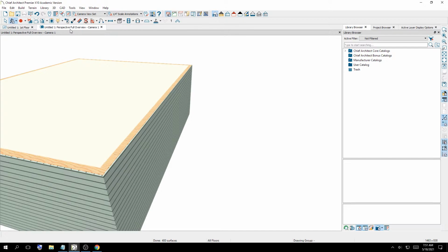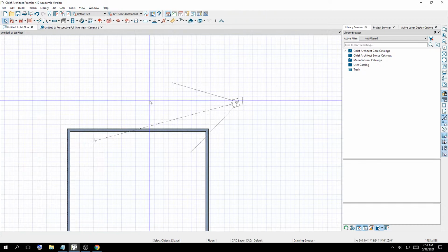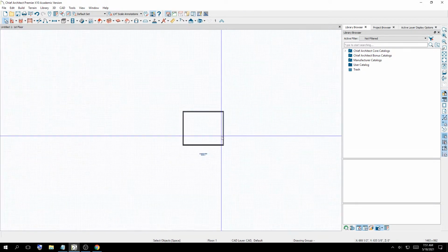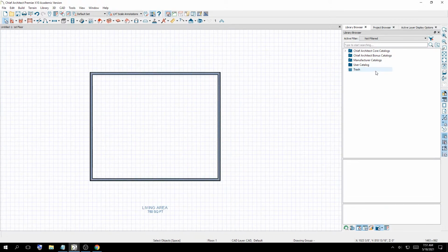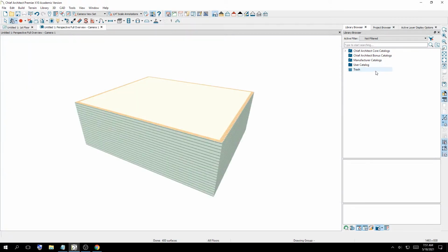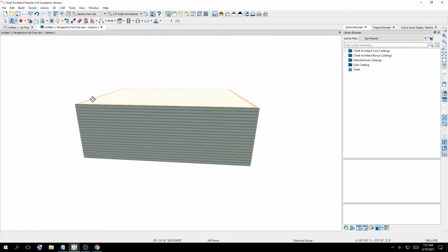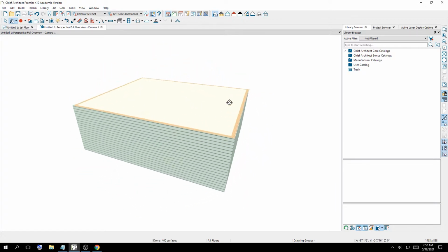It's a pretty useful point at this moment because there's really no intention for me. I don't really care what you're looking at this moment. But if I intended you to see a specific view, this would be important. You can just close this small sub window here, and it would just go away, be back to your floor plan, and your camera is gone. But Shift K on the keyboard lets you quickly view your structure. This is probably the most useful three-dimensional view that you can use.